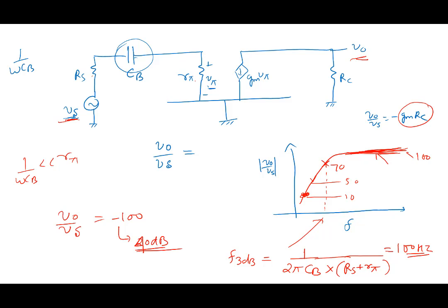Now in speech or music, what do you have? You have 1 kilohertz, you have 10 kilohertz, you have all these different frequencies that are there. And their amplitudes are in certain ratios. High frequency may be high, low frequency may be low, they're in certain ratios. Now if I pass this music signal into your amplifier and you operate it here, what would happen? Different frequencies will get amplified by different amounts. So you don't get that same signal here.